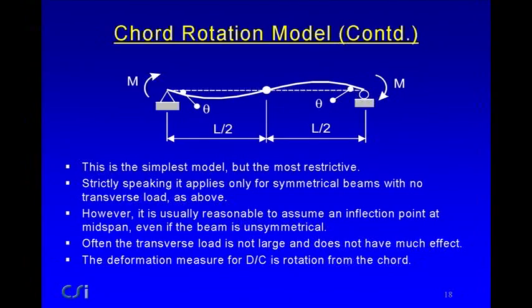Perform implements this, I'll show later, using a thing called a FEMA beam model, which exactly implements the chord rotation model. And the same thing for columns. The reason why it's called a FEMA beam is because this is the only type of model which is actually covered in FEMA 356, or what is now ASCE 41.